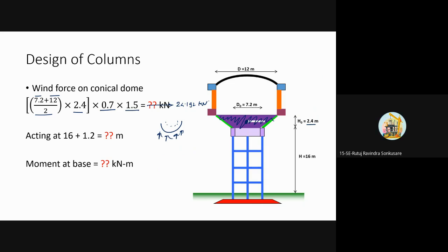So now this force is acting over here, so we have to calculate the height. Basically this is 16 plus half of this 2.5 divided by 2. So this is 16 meters plus half, 1.2. How much is this? 17.2.